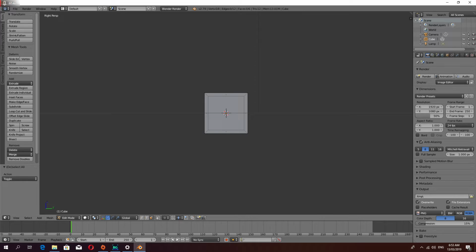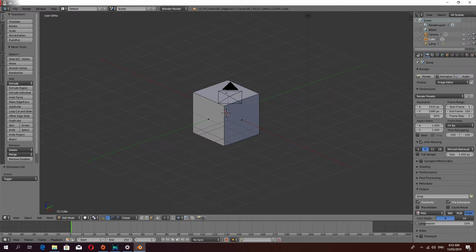These are quite handy. Now, one of the things that you will see here, because I've got this on here, it looks like there's a smaller cube inside. It's actually not. It's just the other side of it, because we're in what's called perspective mode currently. So we've got perspective on that, and sometimes you may want to turn this off. I'm just going to go back to this view here. Sometimes you may want to turn the perspective off. To turn the perspective off, you just hit 5 on the keyboard.